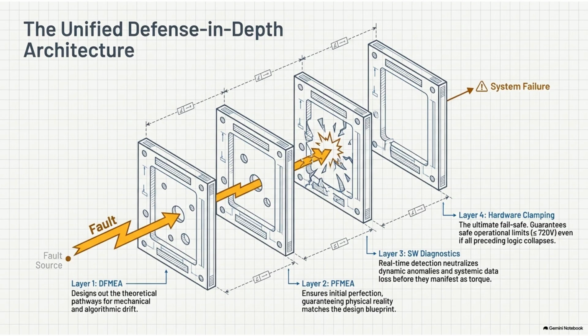Exactly. It is designed to shatter the mechanical bonds. It is actively trying to snap that physical poka-yoke pin we praised earlier. It is trying to find the weak point of the metal. And the success metric to pass this test is brutal. After 100 of those impacts at 150 degrees, the engineers take the motor out and measure it. The mechanical offset of the resolver must be less than or equal to 0.05 degrees. And the TIR, the physical runout wobble, must still be under 0.05 millimeters.